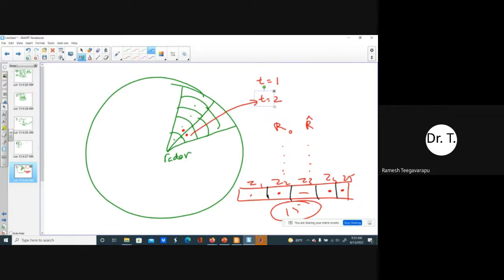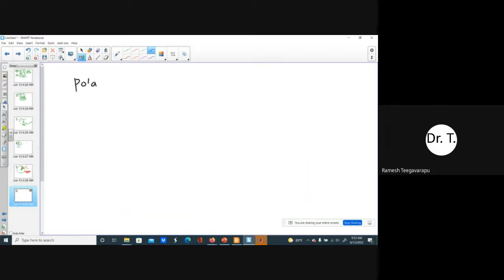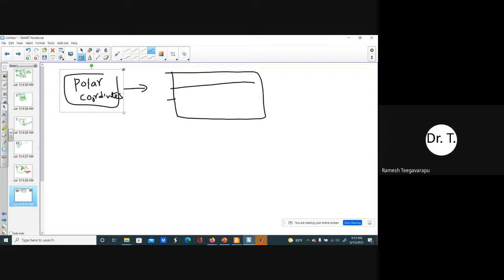In the polar coordinate system, of course, we cannot do anything when we are trying to overlay on top of our GIS coverages. So what we do is convert that into a Cartesian grid, so that we can overlay on top of our watersheds and do the calculations for rainfall values, average rainfall values, or extremes and so on.